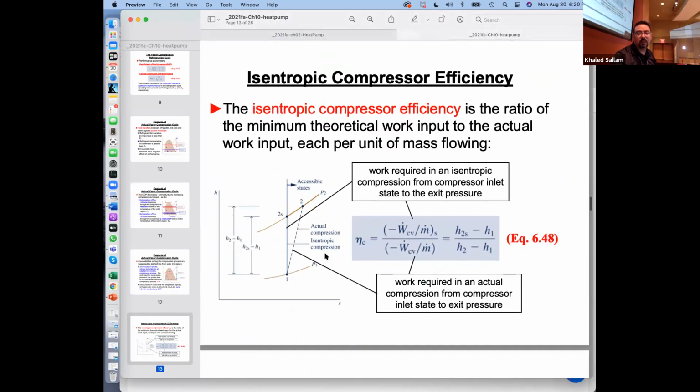right? And we talked about the compressor efficiency. This is the one equation that I wrote for you and it was not that clear, so here it's beautifully written. Eta compressor is small work over big work. What's small? The ideal work. What's big? The actual work. So we use this equation to figure out what H2 is if we know H2S. H2S is easy to get and H2 is hard to get. And notice how 2 and 2S are at the same pressure.